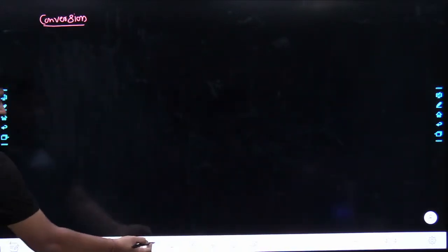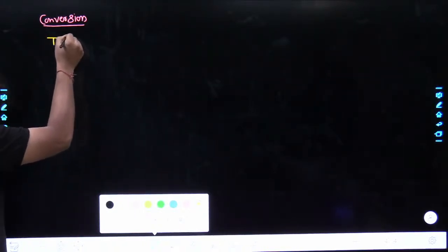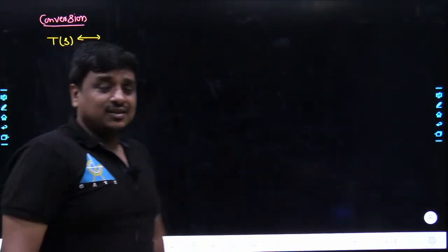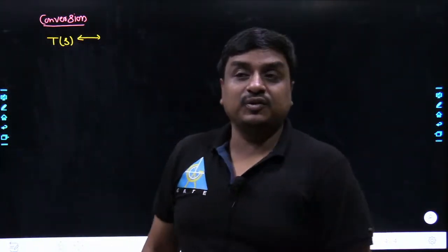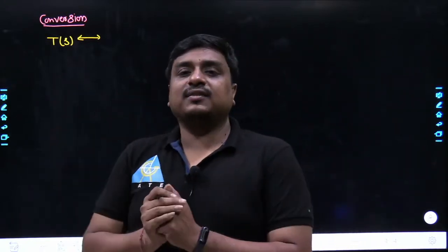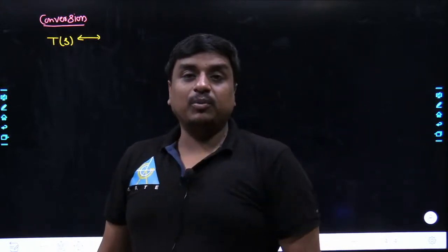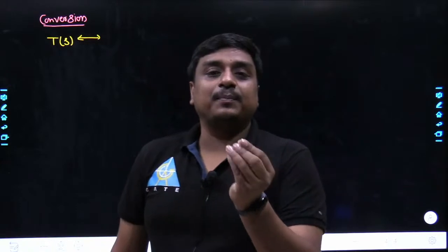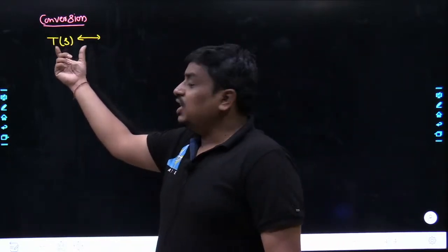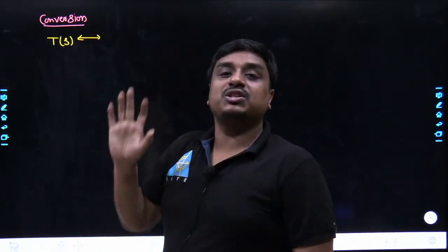Yes, what does it mean by the conversion? That means we would have a transfer function, which would be a function of S. And designing the transfer function is a very tedious task. For designing any given transfer function, you have to purchase the R, L and C from the market. As we have seen in the last class, the availability of R, L and C in the market is not that great. That's the first problem. And with respect to temperature, even the values of R, L and C change. So definitely, the T of S would be in great danger with respect to environmental changes.